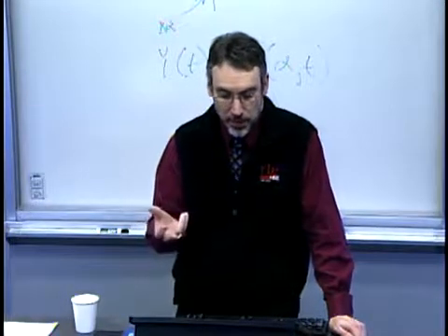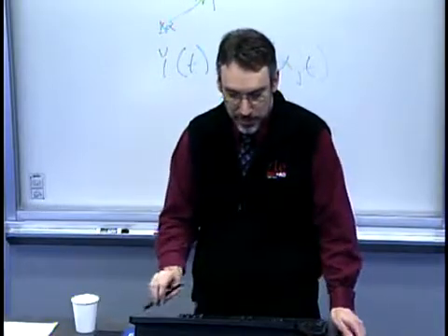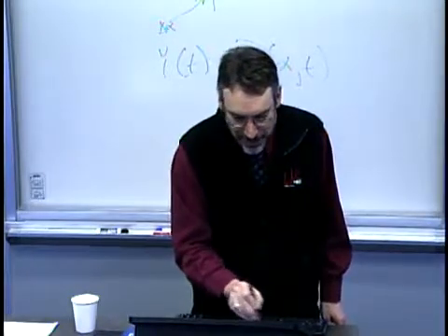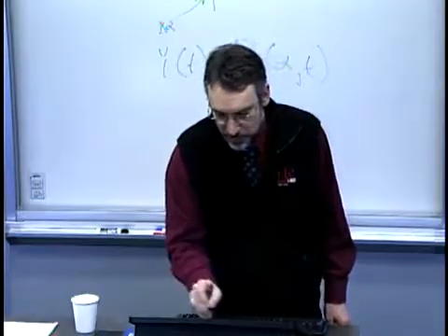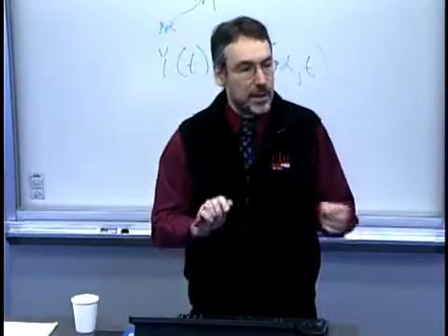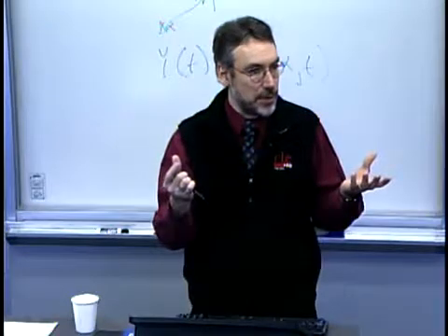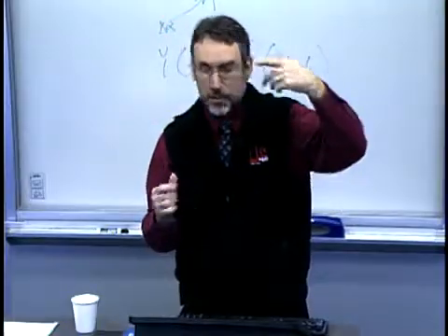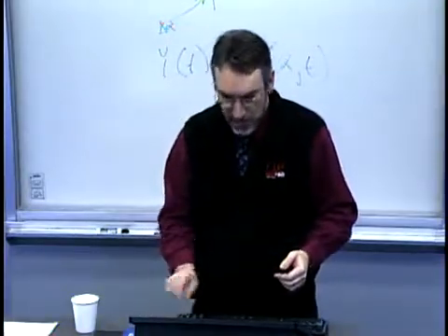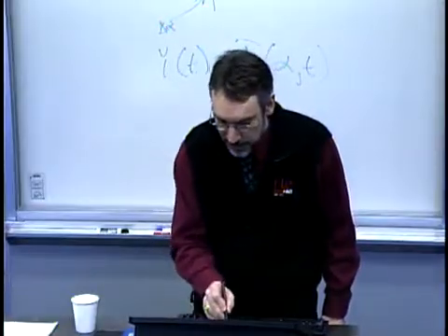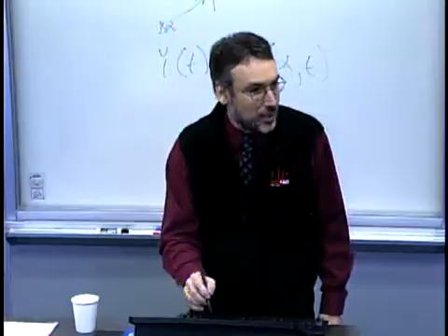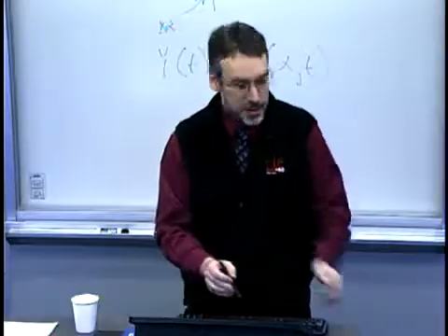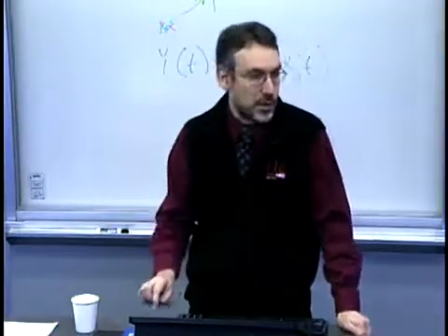Okay. And then the other thing here is, unlike this, we still have all that gook on here, but in here we were basically having a similar band, and it was all just kind of moving or shifting. But the part-to-part variation did not seem to change. The variance of the process did not seem to change. The mean shifted. So that's a very common characteristic that we're worried about. And your point here is that in this case, this looks like a much tighter band, or the standard deviation or the variance of the process in a run-to-run sense is very different than in this process.